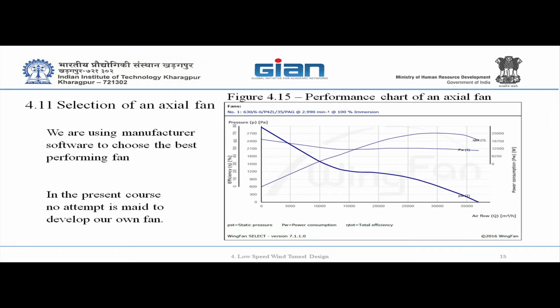So let's say this: if you buy a fan for the closed circuit that can supply a full jet power, then you are set. You get the velocity you wanted. No surprises. And also you get some extra power, and you shouldn't run at the maximum all the time. You can run lower power, lower noise, and whatever.